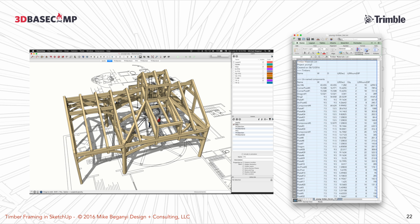So here's my output for this particular model. On the right there, basically an Excel list of the materials. If I had been asked to build the roof structure over this, or if the homeowner wanted me to build a floor system out of TGIs or whatever, I would still use the same plugin to generate that list as well. So SketchUp, if you set up your model right and you think ahead, you can actually get a lot of data out. You can get panel lists out. You can get square footages of your roof, your ceilings, your floors. I mean, there's a lot of data embedded in this model that's handy to use.